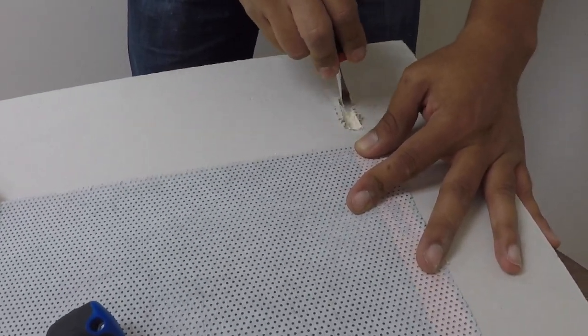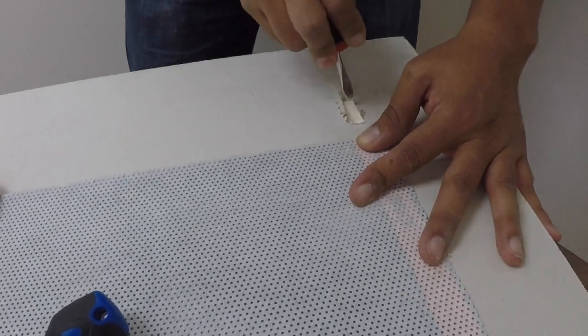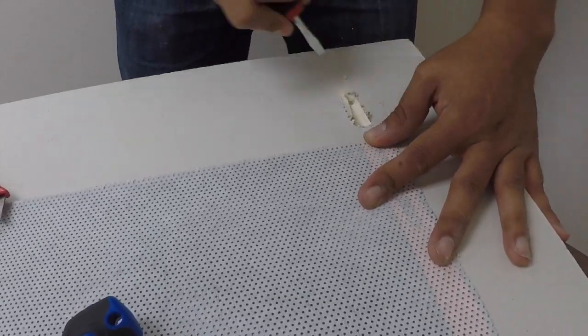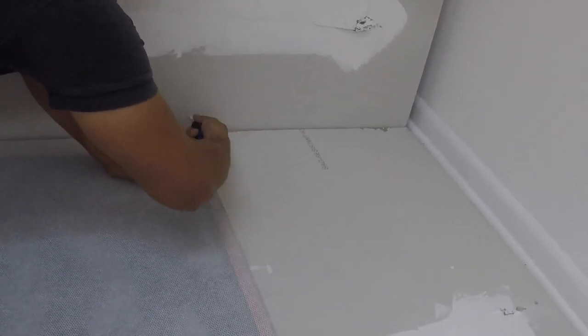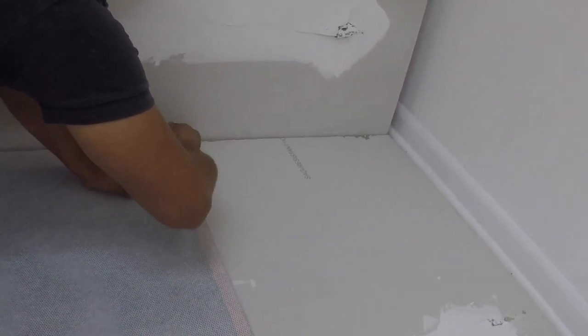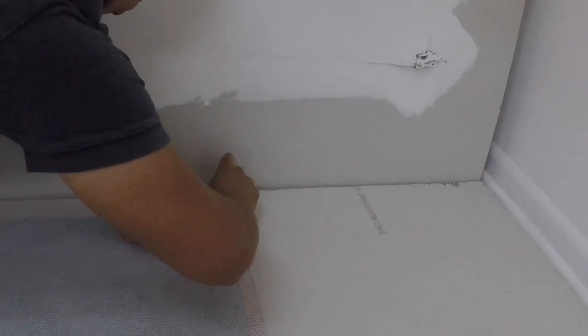For underfloor installations, pass-through holes can be made into the wall closest to the crimped heater strips. Pass-through holes should be made approximately 3/16 to 1/4 of an inch. Any wire that does not end up embedded in the plaster must be routed through a UL-listed conduit.